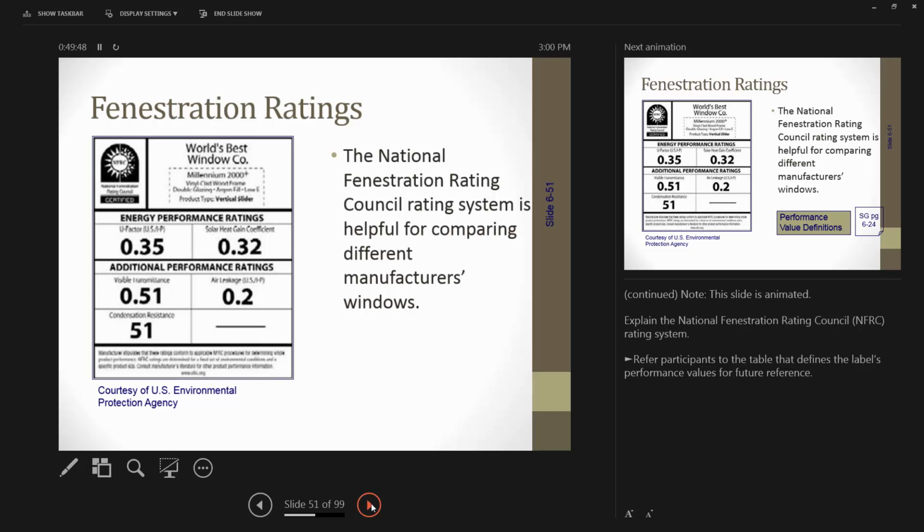Sometimes the solar heat gain coefficient, depending on the climate zone and solar exposure, can help the performance of the window, and this can become important, especially when you're talking about passive solar and passive house design in general, because in order to get the greatest efficiencies out of it, you may end up using different windows on different sides of the house.